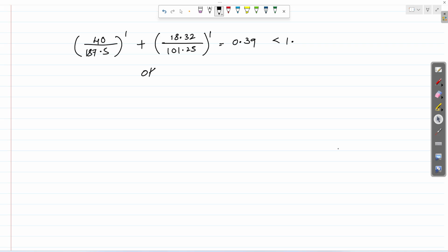So then whatever the column, it is sufficient. The size is also sufficient, 300 by 500, and whatever the reinforcement you assumed, PT 1.6%, it is also correct as long as this ratio is less than 1.